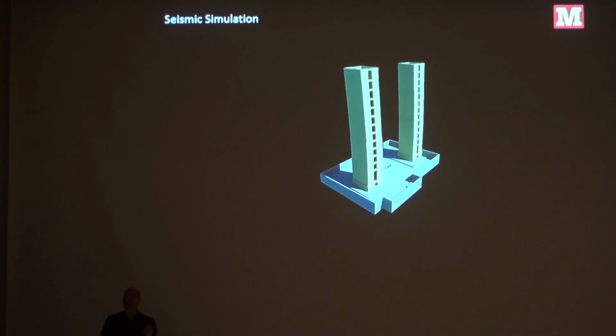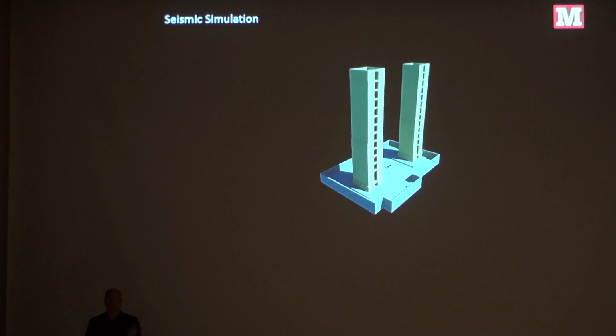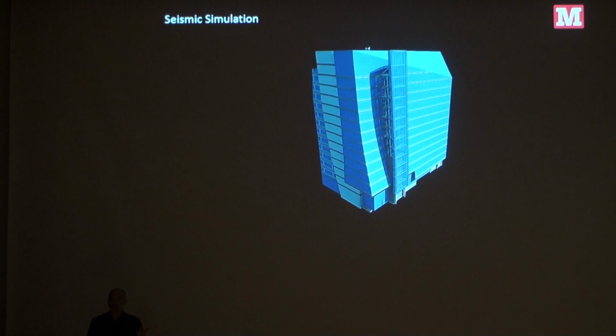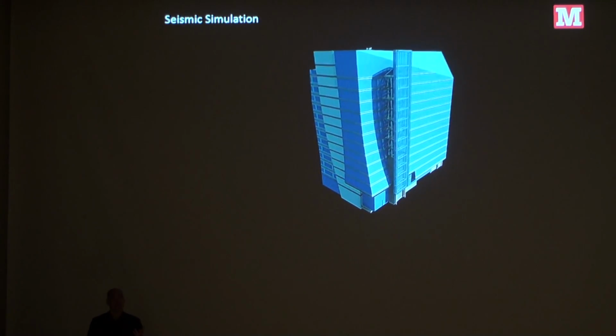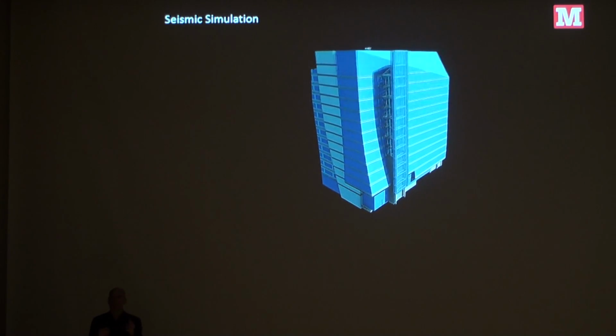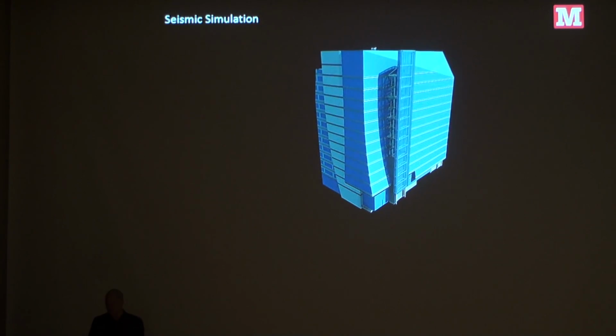We also went after all the finishes. It was about getting rid of the architectural finishes. There was even an element in the spec about the color of the concrete tied to the lighting design, because we were looking at making the lighting system work better and saving money on the electricity. And there was some money saved on improving the thermal mass of the building. So the point is, we found the $10 million by looking at all the other interconnected systems, going back to the puzzle pieces. So when we went from steel to concrete, we were looking at the connective tissue of the entire building and figuring out how we could save every place we could.